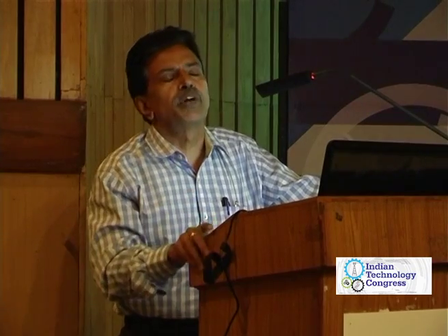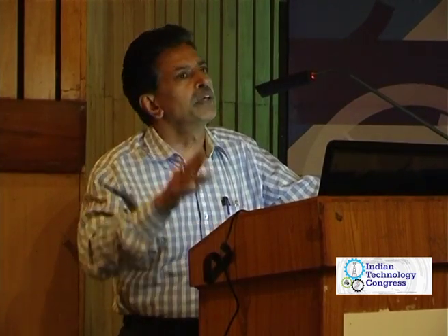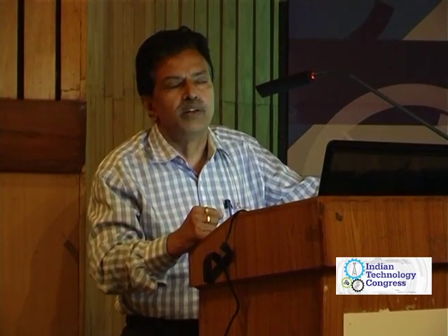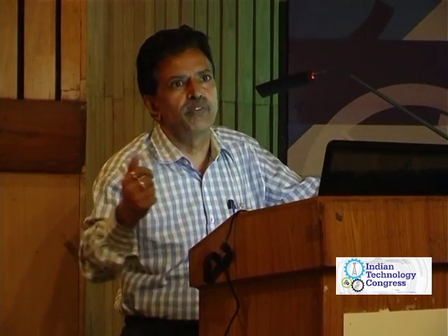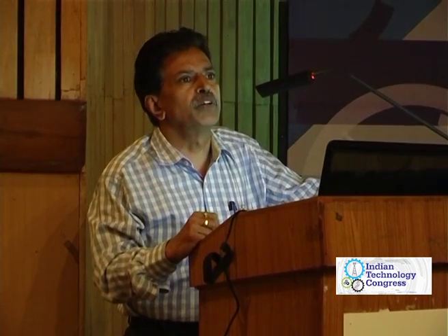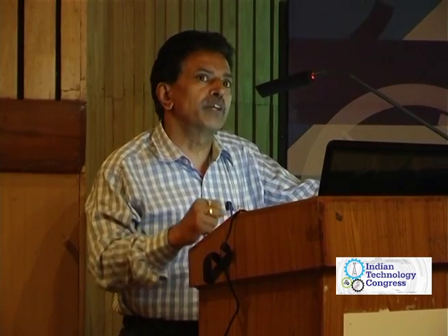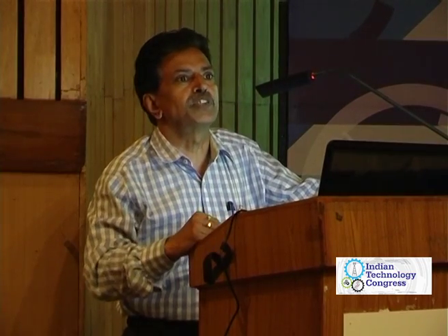So as Professor Shamram rightly pointed out, when we're talking about laminated composites, polymer composites, again the issue is the joining. So how do you join? In fact, we had one common student who was working on bolted fasteners. We are looking at the analysis of fasteners, and there are around thousands of fasteners we need to analyze. So joining again is a major issue, because we are looking at three aspects. In that case it's the interlaminar shear stresses and so on.